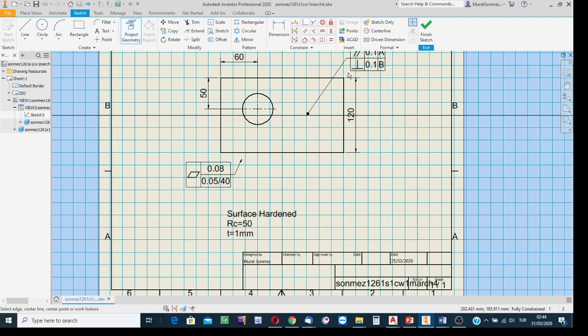But in Inventor and also in any other software, in applying the windowing method, click the left button of the mouse after positioning the cursor at the top corner, and then while holding the left button pressed, move the cursor. A window will appear. Just use the drag technique, and then take the projection into the window and release the button.